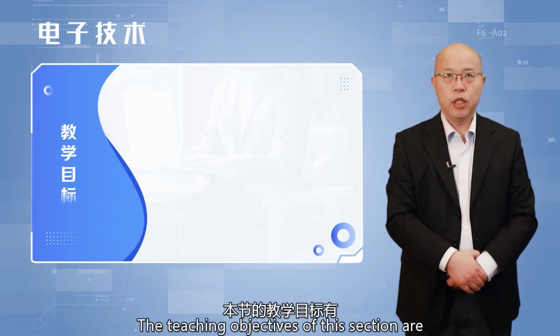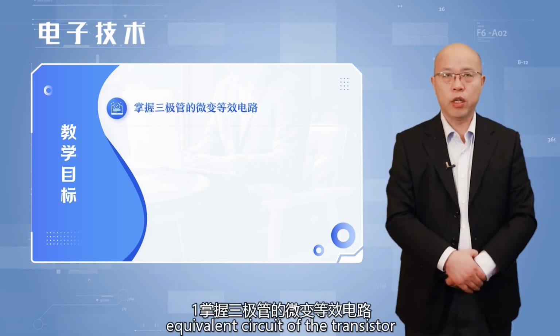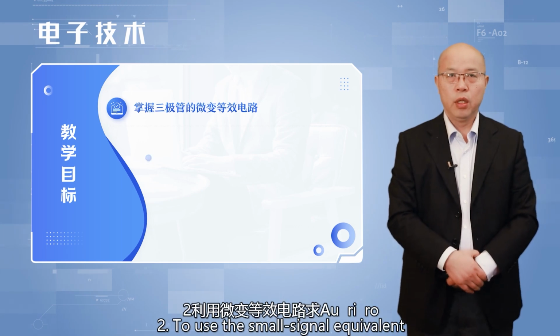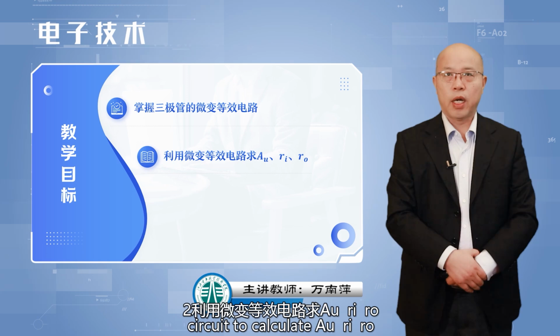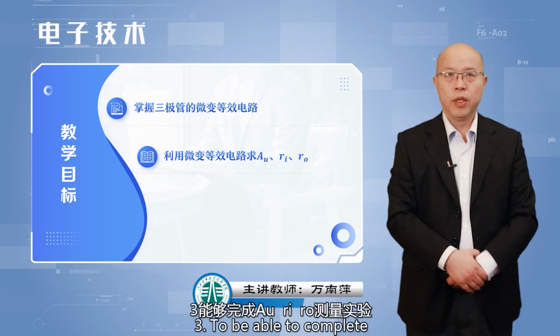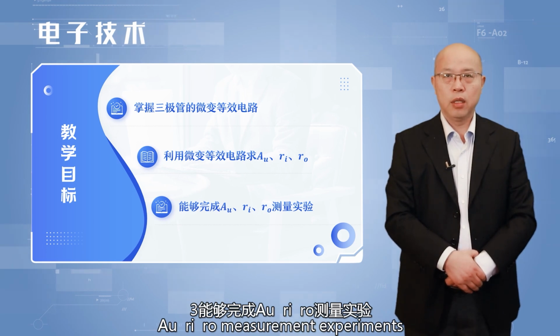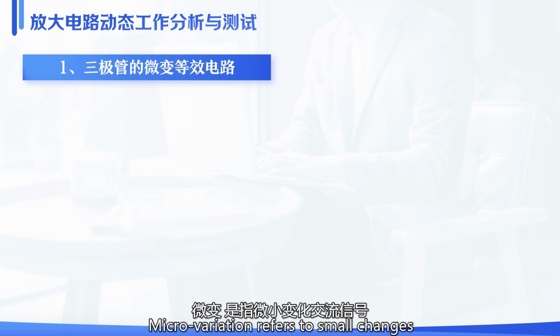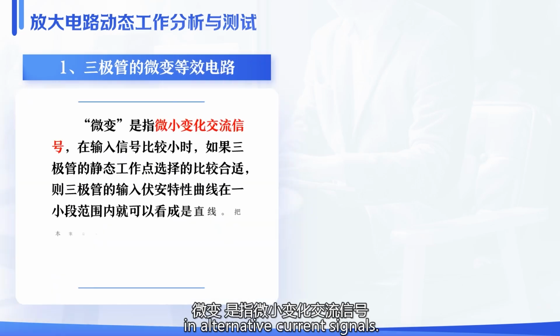The teaching objectives of this section are: 1. To master the small signal equivalent circuit of the transistor. 2. To use the small signal equivalent circuit to calculate Au, Ri, Ro. 3. To be able to complete Au, Ri, Ro measurement experiments. Microvariation refers to small changes in alternating current signals.